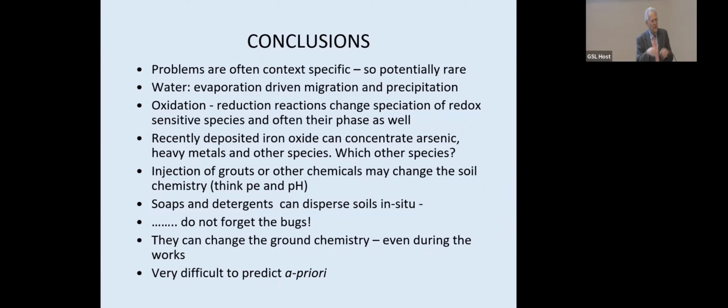Because one of the great debates was what on earth to put round the tunnel as the contact grout when they over tunneled, because cement was obviously going to react with the sulfate. If we used an organic grout, we put a lot of carbon in there, that then might be used by bacteria to reduce the sulfate to hydrogen sulfide.